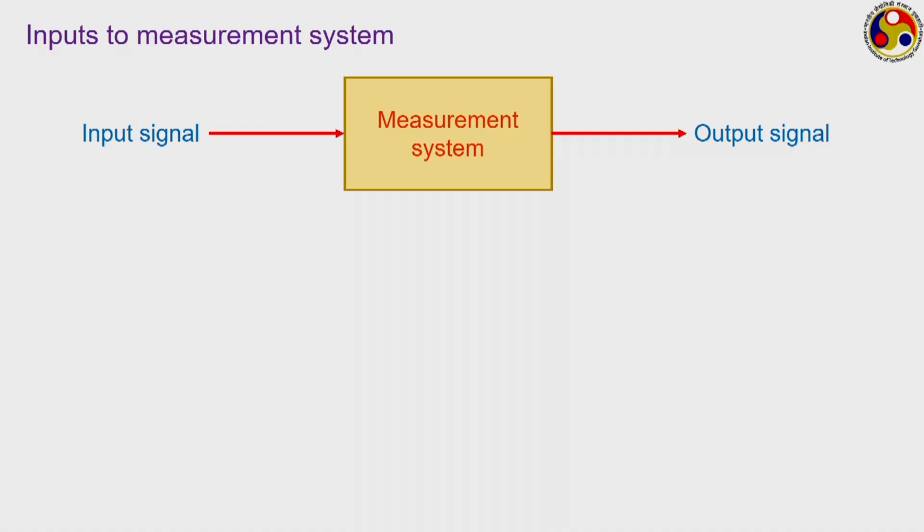But now we are going to talk about the system as a whole. In any measurement system we generally have 2 kinds of interface. The input stage creates an interface between the physical system and your measurement device, where it collects the input signal from the physical system. Quite often that input signal is compared with some kind of standard reference to provide a transduced signal, which goes to the second stage, the signal conditioning stage. The processed output signal which comes out of it is supplied to the output stage, the third one, which creates another interface between the measurement device and your recording device.